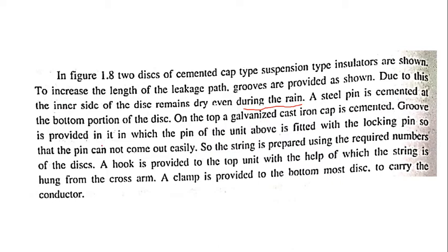Okay, the groove is provided in it, in which the pin of the unit above is fitted with the locking pin, so that the pin cannot come out easily. We need to remember that the pin should not come out easily, because we are going to place it in the groove of the suspension type insulator. So the string is made using the required number of discs.